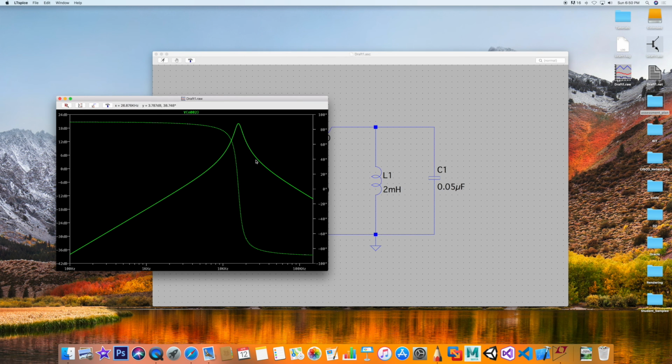Again, below a certain point, depending on what you're doing, you're interested in this. This is the significant value. This is just showing you the trend as to what's going on with the total impedance. So we have enough information at this stage. We could see the angle shifting, and we could see our peak, or where the resonant frequency is for this particular configuration.